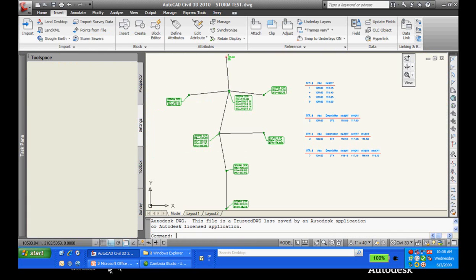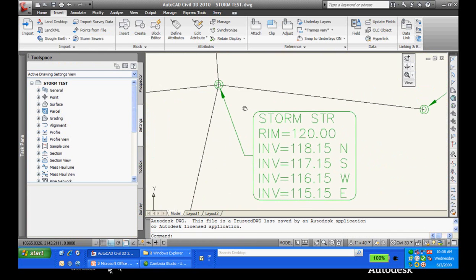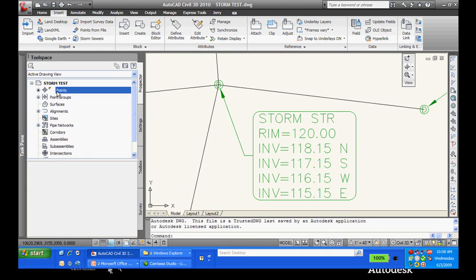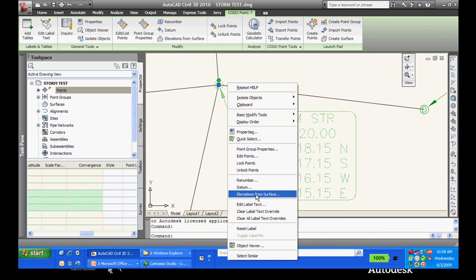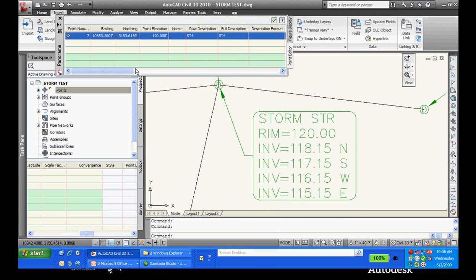Those values that we use to extend the database, here is an example of that. I've extended the database on my points, such that the points themselves now maintain invert values. So I did the exact same thing we just looked at, except instead of making a tree DBH, I came over and created import or invert 1, 2, 3, and 4. So these are the values that I dropped when I got to the manholes. And then what I did is I created what's called an expression. I said take the rim, subtract invert elevation 3, and tell me what the actual invert is.